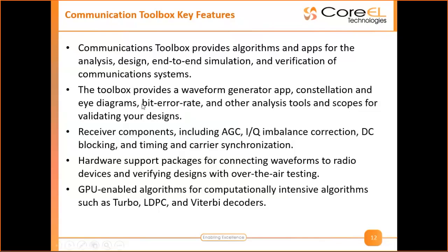So you can calculate the bit error rate. Once you transmit it out, at the receiver end, you demodulate the signal, extract the bits from your received signal, and then compare it with the transmitted signal and calculate the bit error rate. That is what bit error rate is, which we'll be simulating, which is a major criterion for us. A good communication system has low bit error rates, since the signal is traveling through a physical medium such as air, or it might be underwater, or through many different weather conditions. You should not have errors in bits, or else you will not get accurate data at your receiver end. So we will see how we can model and simulate this analysis.